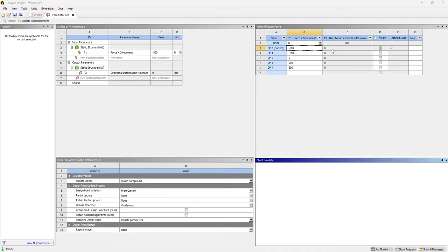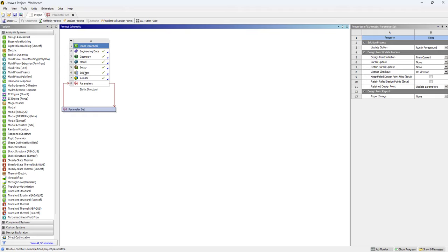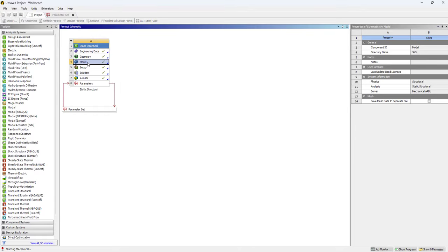After the solution, you can see that the results are not as we were expecting. All of the results are 0. There is one particular thing you need to take care of when parameterizing the details: whether the output that we are looking at in the parameterization tab is sign sensitive or not.